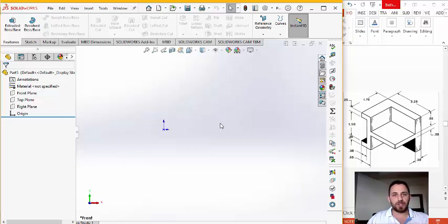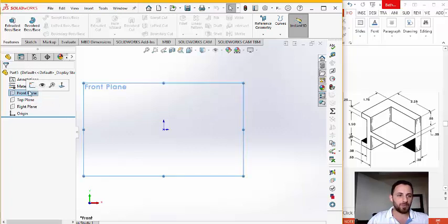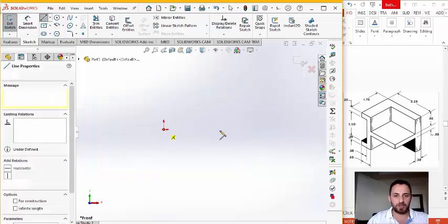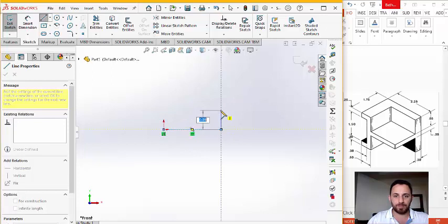And we said on a previous session as well, it's important always to sketch the geometry, the first step. The second step, you add dimensions, and finally you add features. So I'll start from the front view, sketch. This is the front view. So I start sketching the shape.